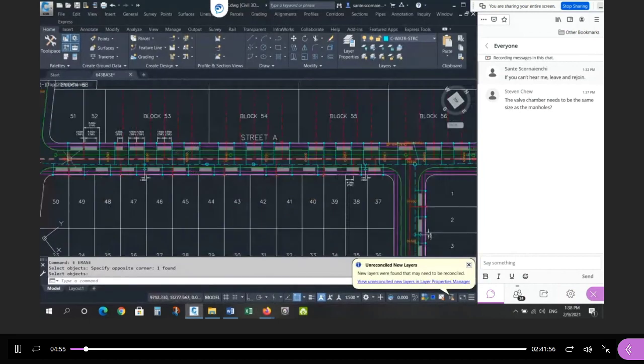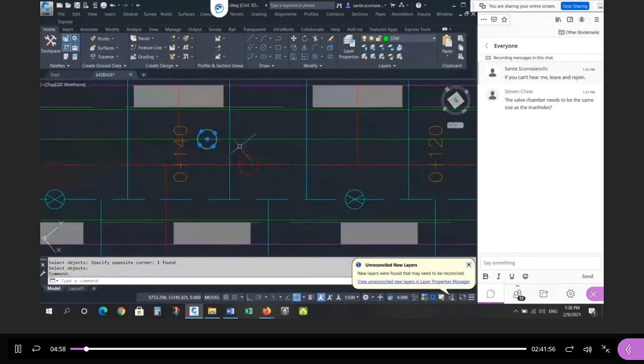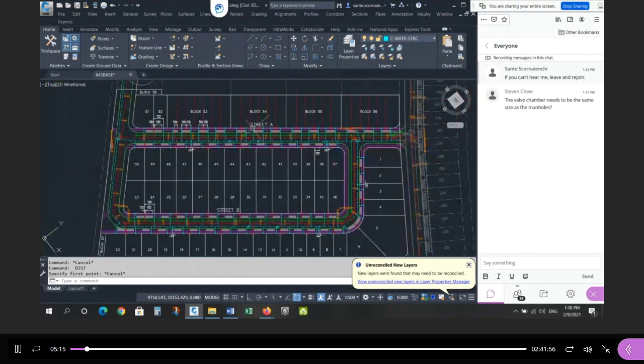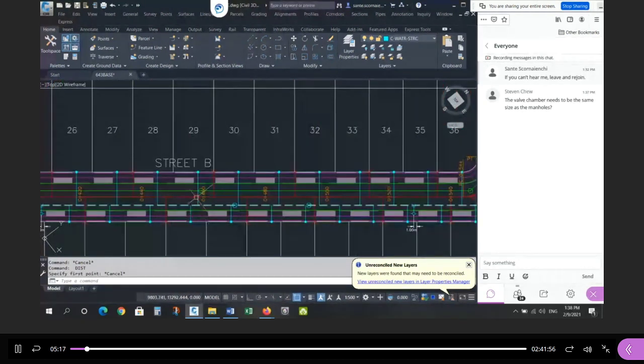Okay, so what happens along the typical stretch, you still have to pay attention to some of the details. Like, where did you put these two maintenance holes? Some of you had a pipe that stretched from this intersection all the way to here. It was too long. You actually need a pair of maintenance holes here. If you measure the distance from here to here, you'll notice it's more than 110 meters. So you do need a pair of maintenance holes here and a pair of maintenance holes here for the same reason.